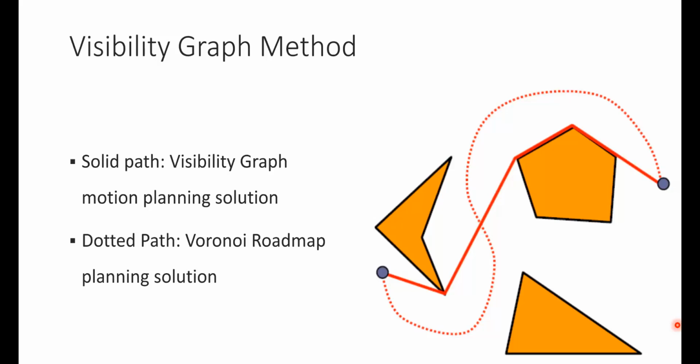If you have a LiDAR, let's say, so you have a point cloud of your environment, then you'll basically try to fit some lines to the exterior of each of your obstacles. And where those lines intersect are going to give you your vertices. So that's just one idea, but pretty much anything that you can do to that sensor data that will give you the exterior of your obstacles. Got it.